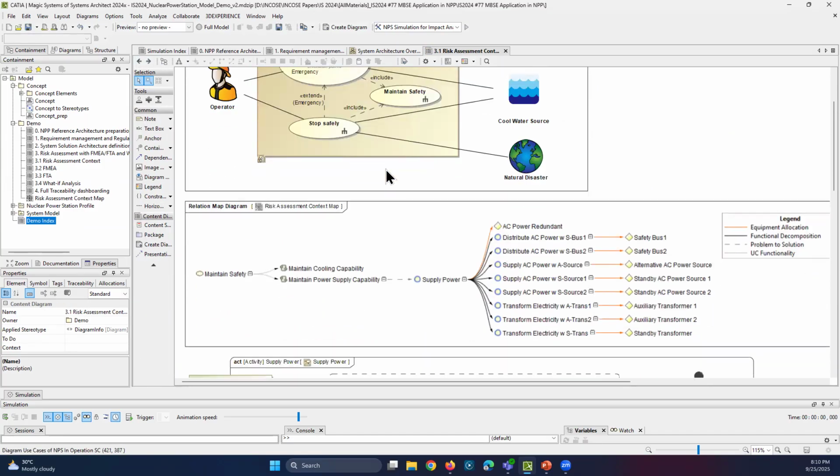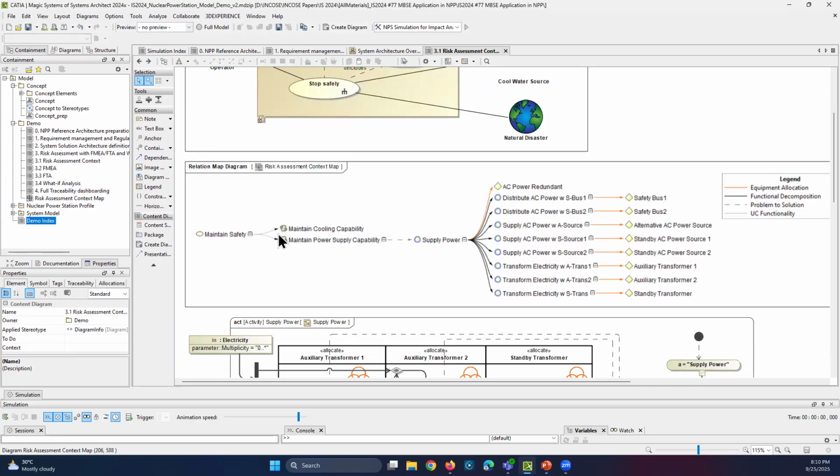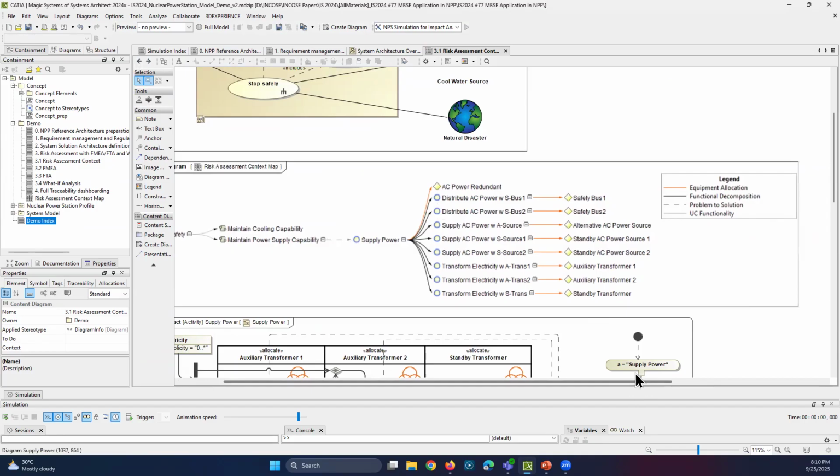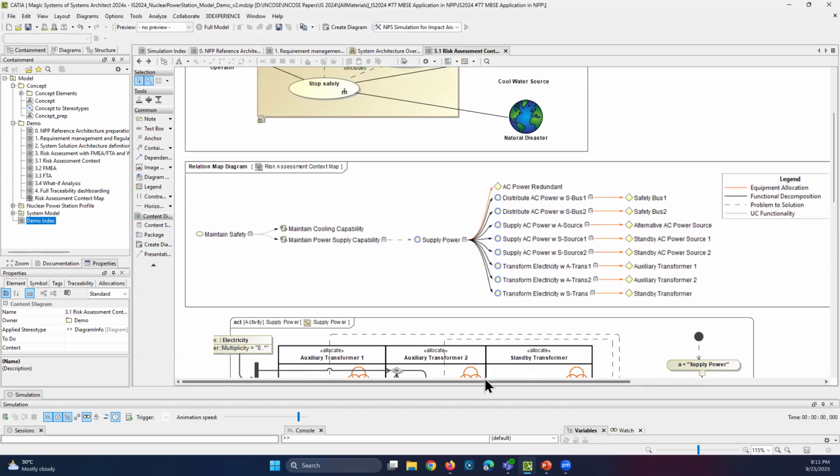So in this system, as mentioned, you can see the detailed traceability from the elements. And you can see most of the traceability relationships here are not manually created, but rather are automatically created based on the relationships among the elements when you build the use case and activity diagrams. So the end-to-end traceability can be presented not just in table form or dependency matrix, but also as a relationship map like the one that you see.